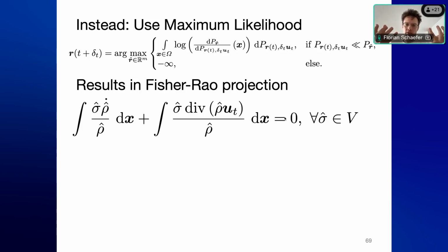For instance, the way you easily get negative energies in these equations is if your momentum transport term transports a bunch of kinetic energy into a cell without you transporting enough total energy into that cell. And then you divide the two from each other and you end up with a negative internal energy. That's why this approach that we're working on currently suggests a natural way of coupling the evolution of these equations.